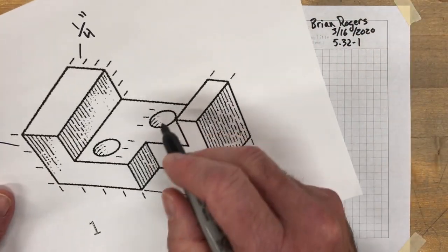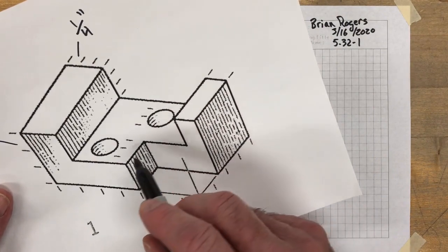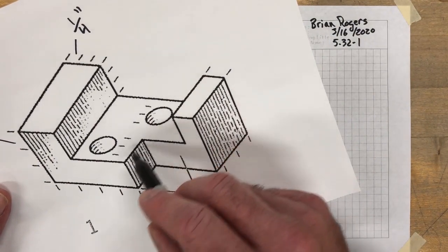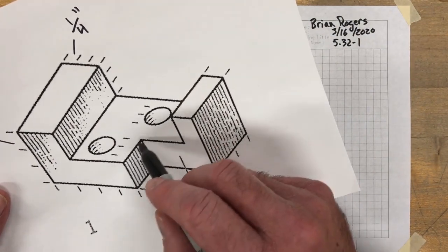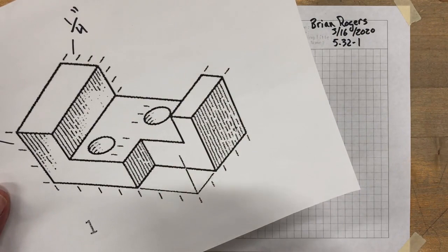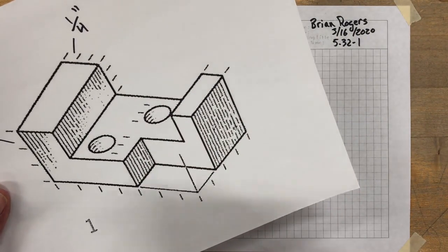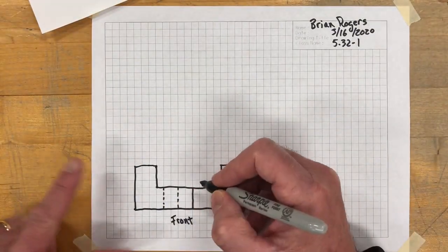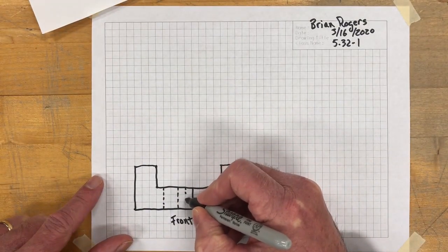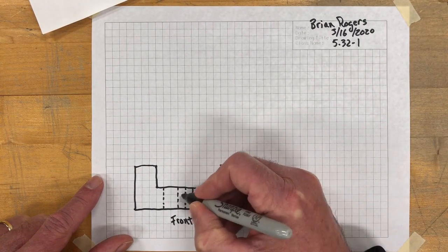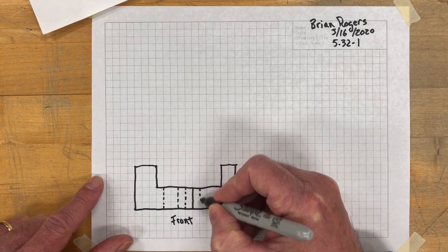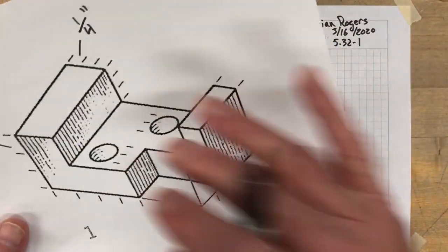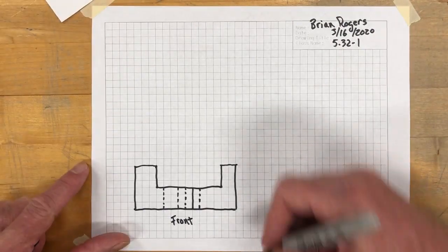Now the right hole, what we have to do is, after much puzzling over, I've kind of decided, and it makes sense to me, that this hole is centered right on this edge right here. All right, so it's 1/2 inch in diameter. That means 1/4 inch of it will go on either side of this edge. So what does that mean for our drawing? Well, I'm going to go ahead and put a hidden line right here, and then measuring over 1/2 inch in diameter, put a matching hidden line over there, and that's both the right and left edge of that hole for this backmost hole. Okay, so the front view is complete.